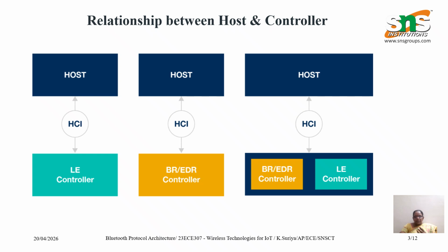So the host can be seen as a computer running Windows that receives the processed Bluetooth packets and communicates with the user applications, while the controller would be the Bluetooth USB dongle that runs the firmware and performs low level tasks such as capturing the packets, announcing the device, channel synchronization, etc. Host and controller communicate with each other using the host controller interface, which is known as the HCI.